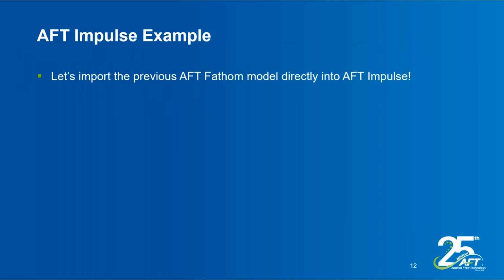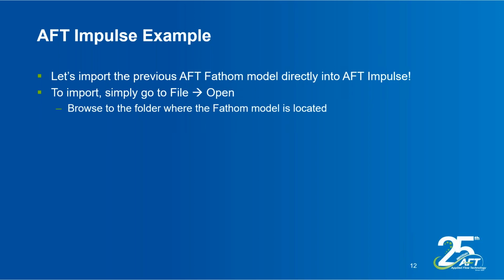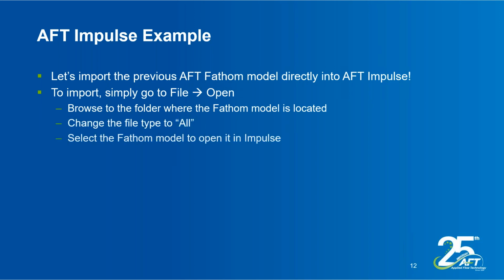Okay, so for AFT Impulse, I already did import the AFT Fathom model into Impulse. This process on this slide illustrates how you go about importing a Fathom model into Impulse. To import it, you simply run Impulse, then go to File, Open, browse to the folder where your Fathom model is located, change the file type to all, and then select the Fathom model you want to open, and then that'll open it up right in Impulse.